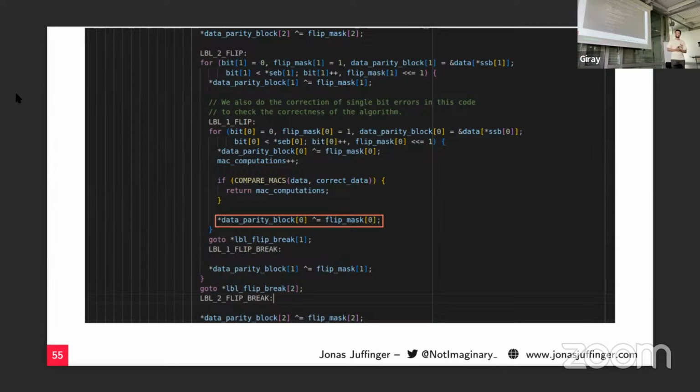But I'm proud. Before coming there, so I understand that you already have the computation unit for Mac implementing your memory controller. It's also in the CPU core. Yes. So yeah, I'm going to question the necessity of that actually. So on top of that Mac computation, what I see here is like some shift operations, some masking, and these are very cheap operations to implement in hardware.